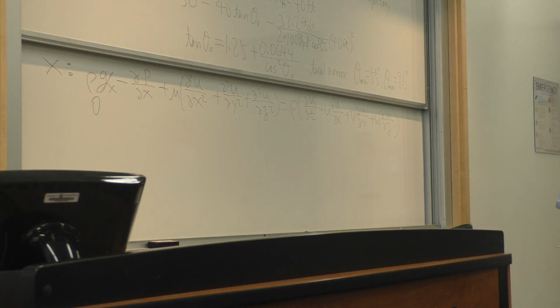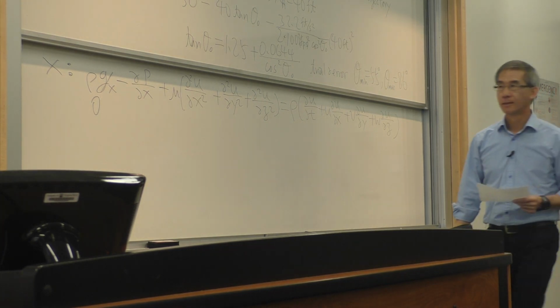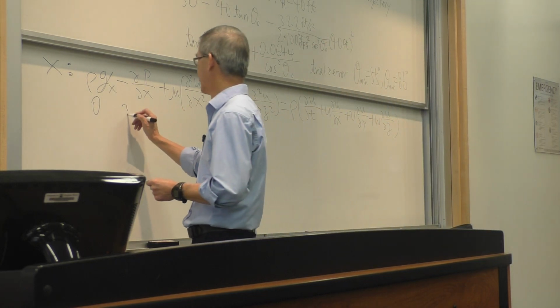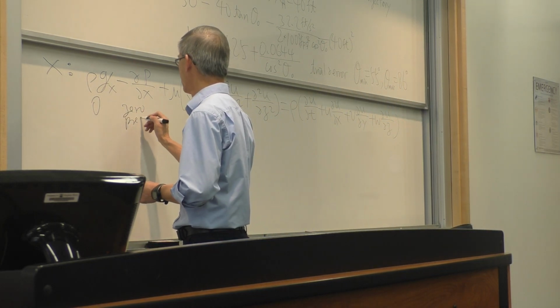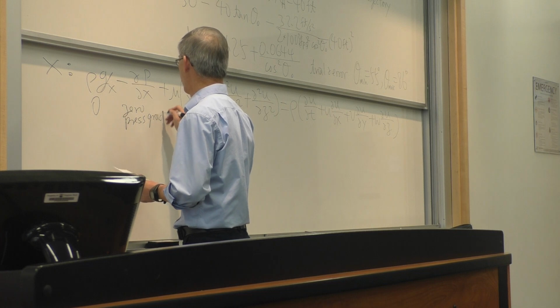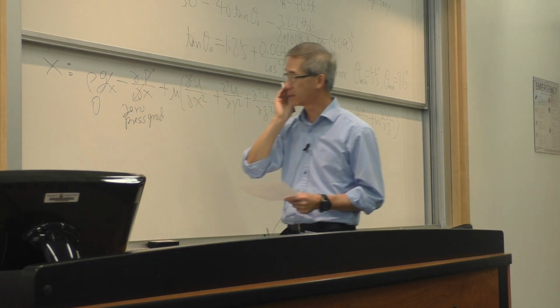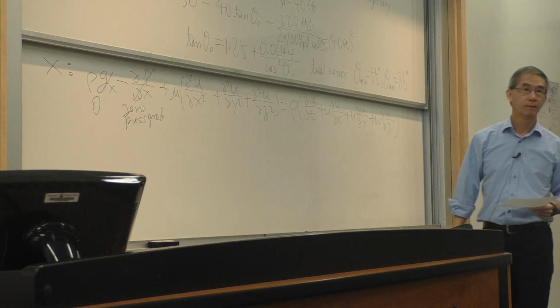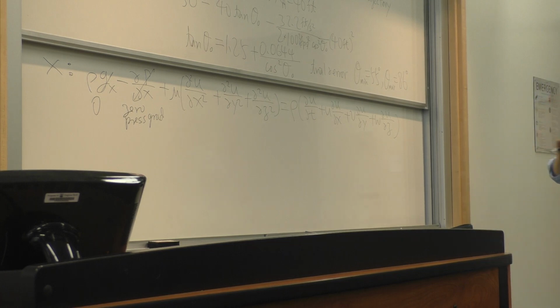dp/dx. Why? Because I said so. Very good. This is a very important reminder. 0 pressure gradient from the problem statement, not because it's otherwise. And 0 pressure gradient meaning you have just a very simple flat plate, and it's the basis of what we start our analysis. A spear, a missile, or a turbine blade is obviously not 0 pressure gradient, but that's beyond our comprehension.